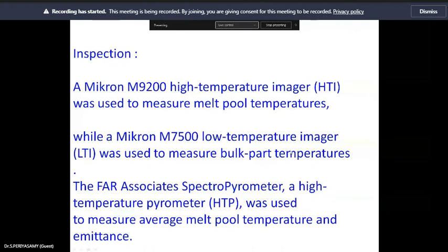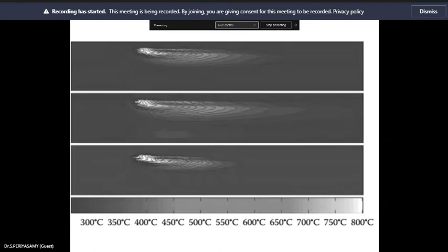variations within that. Because of the hot pool or melt pool, the cracking and other issues are initiated. In the sense, you have to monitor all these things using a pyrometer. The pyrometer will give the temperature at a particular point. Suppose you go for a high temperature imager, it will give the entire temperature image. So you can identify where the temperature at the pool is high and low, and how the stress will be formed. So you can get an idea of this.